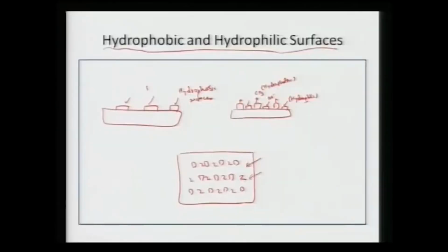So, if a water droplet falls on this particular substrate, it will stick because it has localized hydrophilic regions. At the same time, if an oil spills onto it, it will still try to stick, because again you have certain amphiphilic regions available on the patterned surface. So, we can achieve dual functionality or duality in a particular surface, or if you want to control it vice versa, we can also eliminate that particular part by controlling the hydrophobicity or amphiphobicity on the patterned surface.